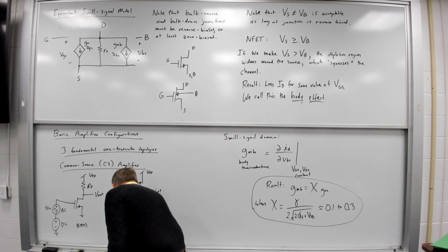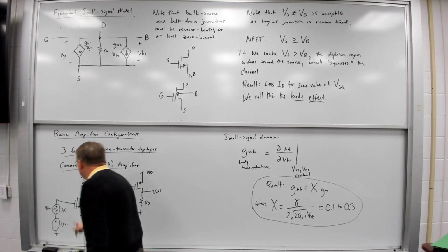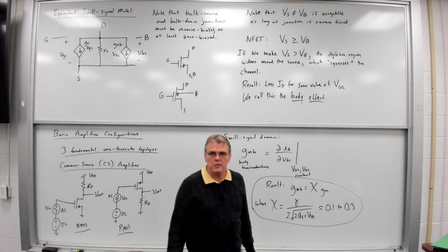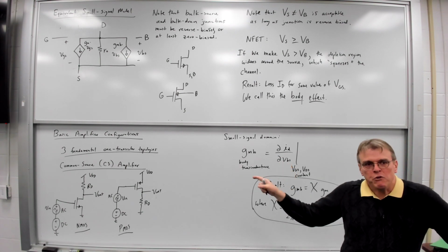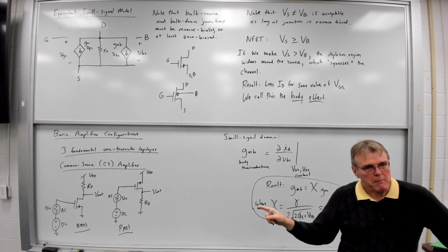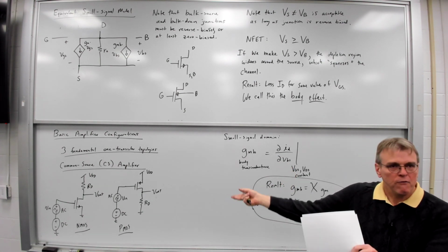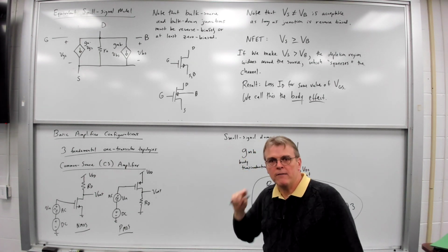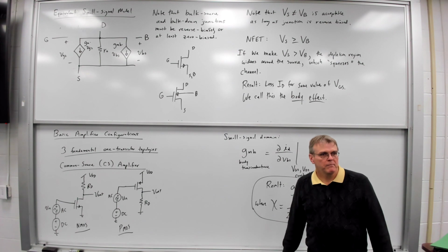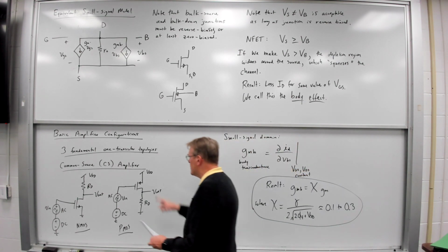Now, I point this out because many times, guys, in the examples in class, I'm going to draw the NMOS version. But if you can do it in NMOS, you can do it in PMOS. You can always flip the topology upside down and replace the NFET with a PFET, and it will work just fine. Okay? That's our first topology.